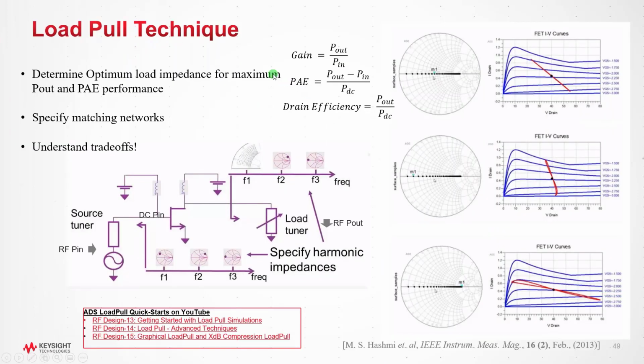So we're going to look at two things, load pull, and then we're going to look at it in large signal conditions to kind of validate the model. We're going to use ADS, but as Abby said, there are other tools that you could use. I'm partial to ADS for several reasons. On the load pull side, one, you can import measured data very easily from, like, Maury or Focus Microwave. Number two, you can easily draw the contours, and I'll show you that. Number three, you can find the optimal load. You can put in different types of reflection coefficients. It could be a circle, a rectangular region, a pi region at the harmonics, and find the optimal load.